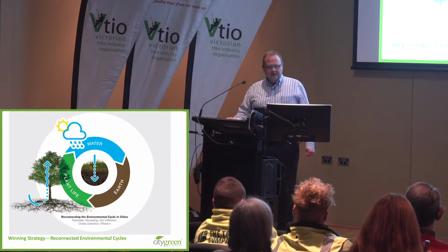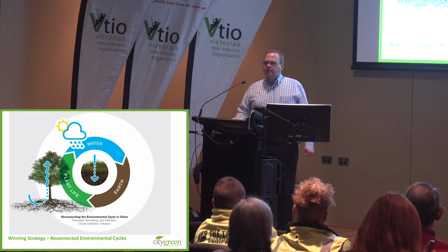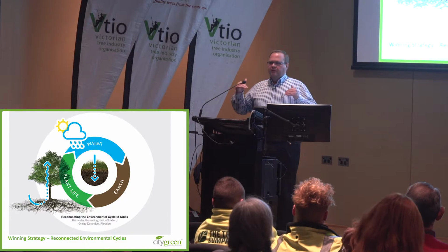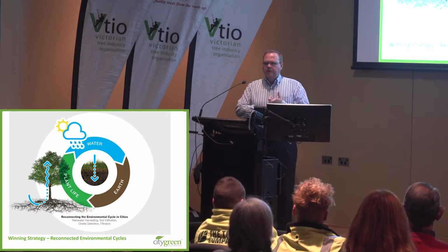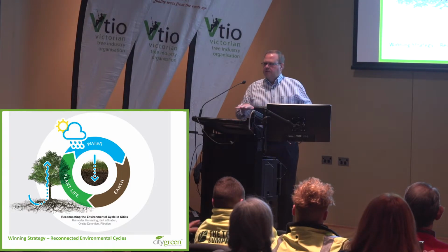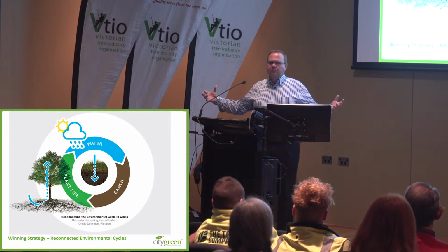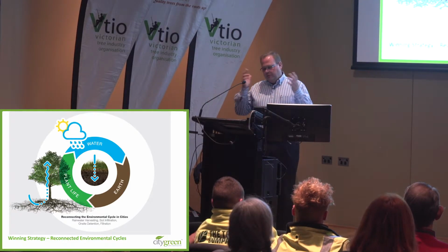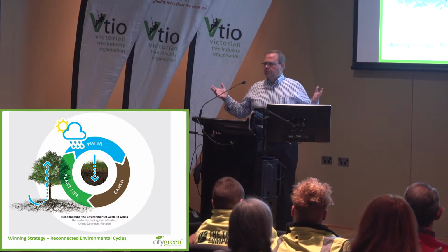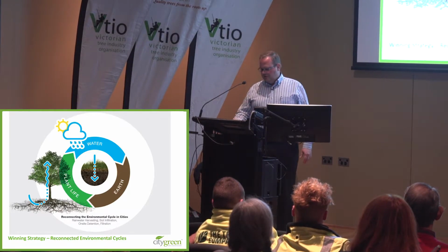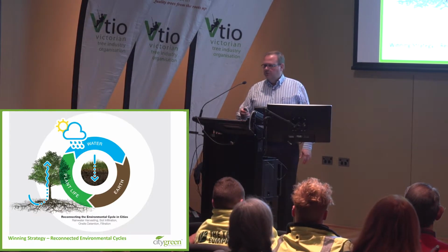So what we're about is capturing that water, bringing it down through the pavement, which we can do via permeable pavements or rain gardens or strip drains or whatever, and getting that into the loam soil underneath, where the tree's root system can access that moisture, suck it up, pump it out via evapotranspiration, do the cooling and the accelerated growth that we're looking for.